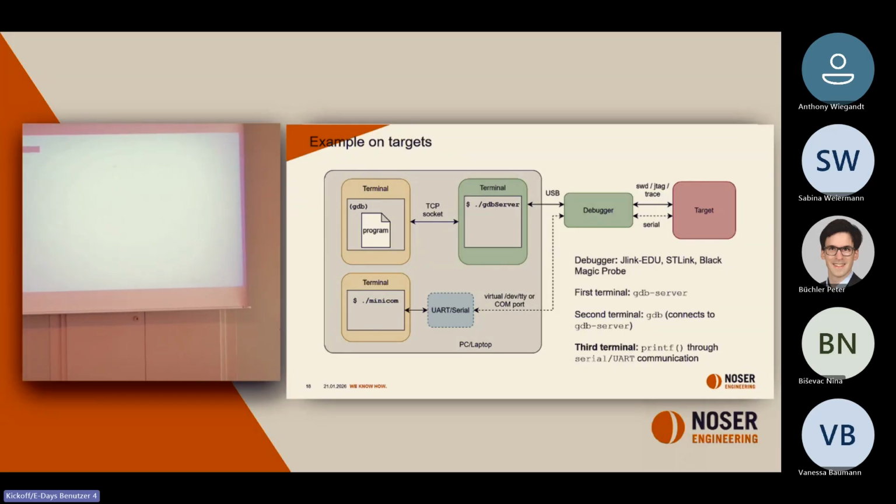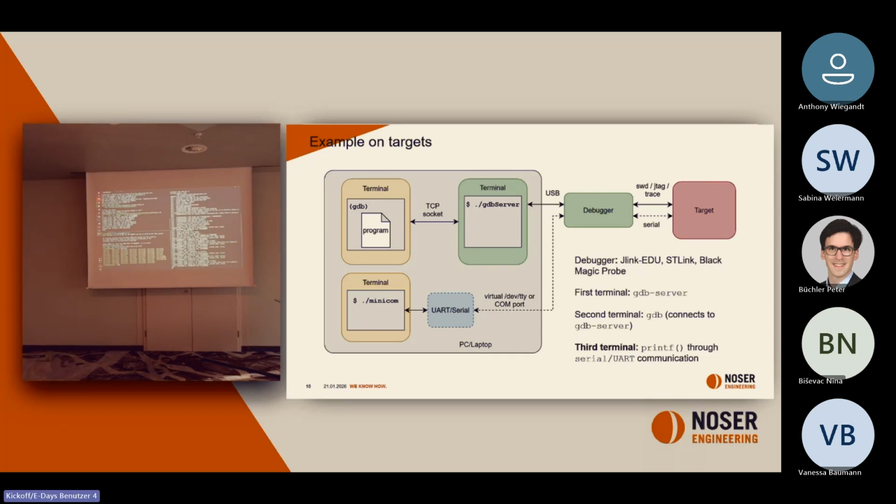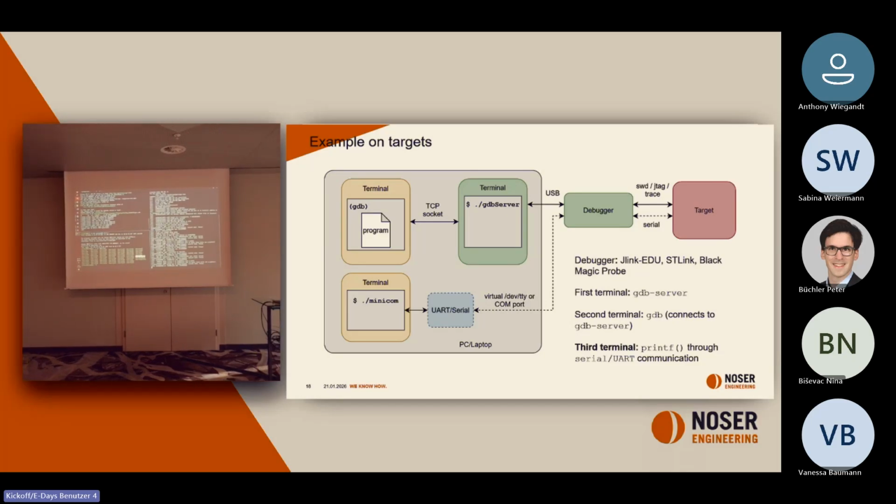So in 3 terminals, like a fully development environment, if I do dev tty, we can see here a beautiful device. And so just to know, ACM means ARM Cortex-M. Very useful acronym to know, that I discovered a little bit later. And I can do Minicom on a device /dev/ttyACM0. It's ready. Here I can do run. Yes, up. I see my message. I see the thing working. So here, 3 terminals, full development environment.